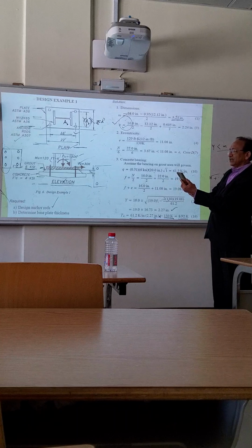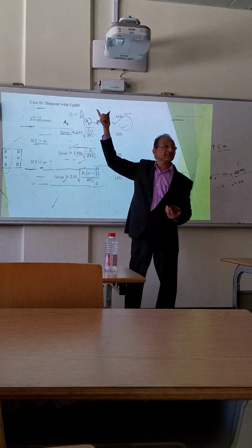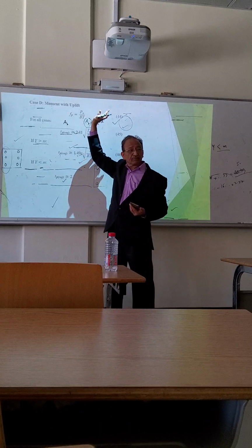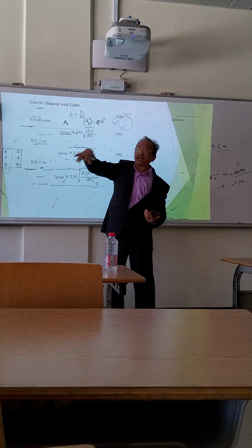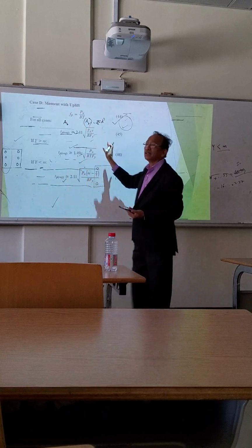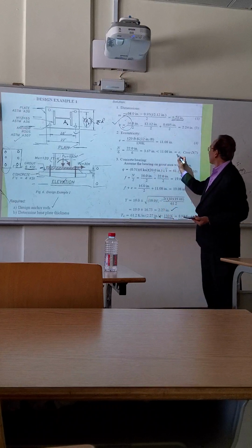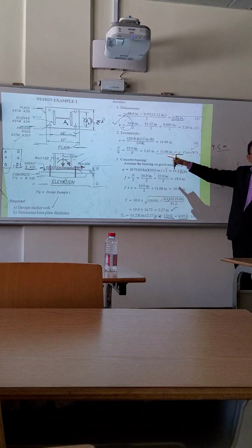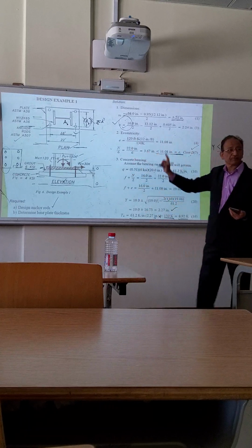Again you can see here how we know Y is less than M. It's case D. What is case D? When there is moment. Case C also has moment, but in case C there is some limiting value, N by 6. Here it is more than that. You will decide by the eccentricity, so first you check which case this is. We did that earlier, in the beginning. Depending on the value of E, we decided which case this is. That's why we first calculate the value of E and N by 6. That will decide whether it is case D.